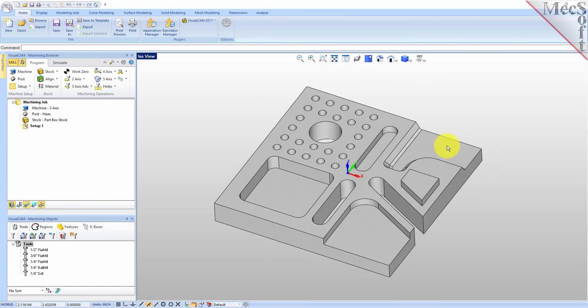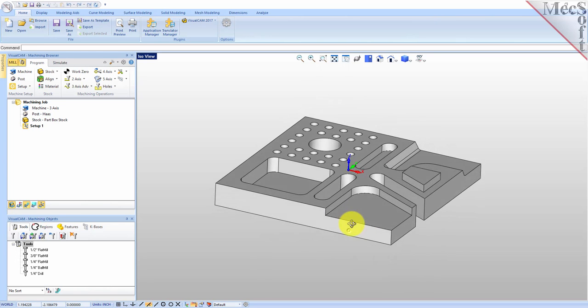And this feature on the back is a 3-axis pocket feature. It's 3-axis because it has a contoured drafted surface and a fillet at the bottom, which you need 3-axis machining to complete.